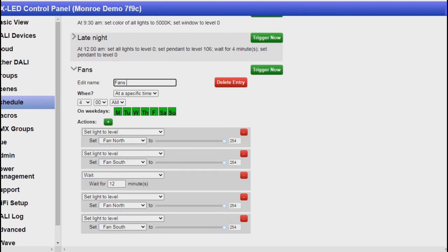on the fans, the fan timing, and the operation. Our fans actually are designed to turn themselves off, so they're designed to self-time out. That means when you turn the fan on in a bathroom, I'm talking about exhaust fans here, when you turn the exhaust fan on in the bathroom and you walk away, it will turn itself off after a defined interval. So we have these exhaust fans, and we're able to change the timing on these fans.